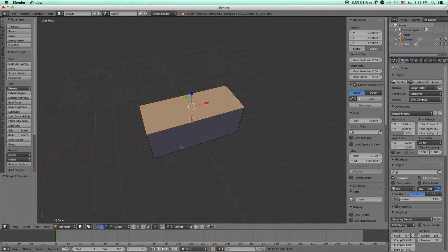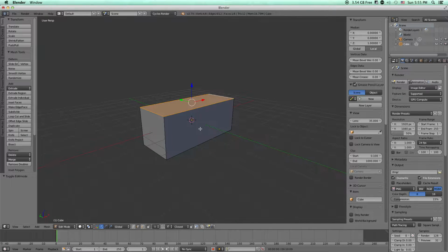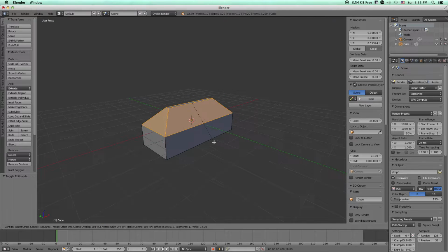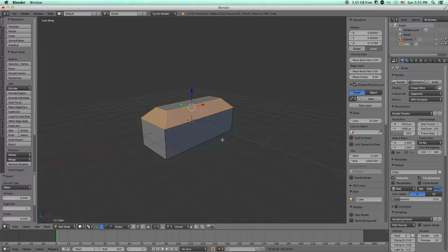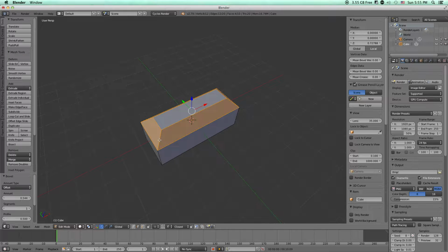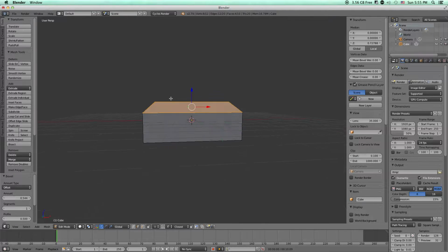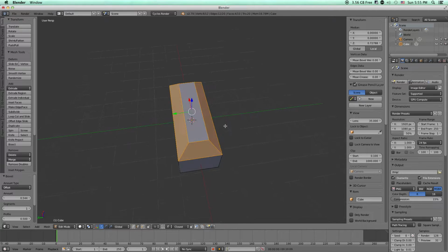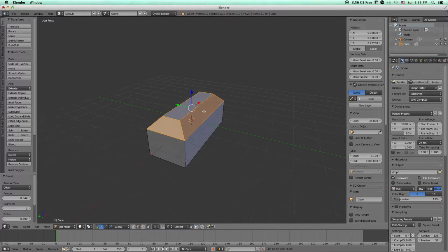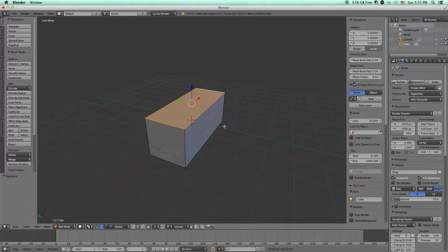So now if we go into edit mode, grab those same 4 edges, Control B, you'll now get what looks like something uneven here, but all of our angles are exactly the same. So it's a perfect bevel all the way around. And you can always undo.